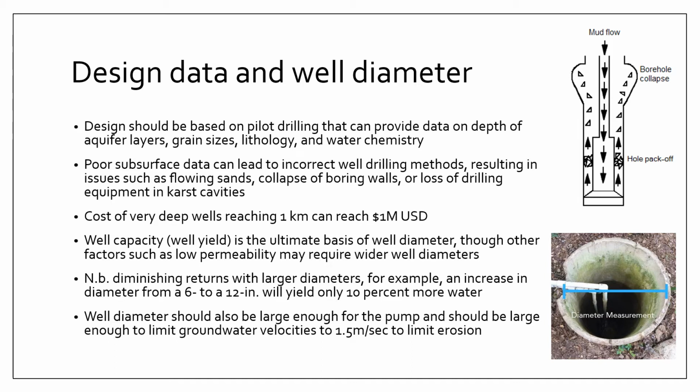So it's important to have initial subsurface data so that a proper drilling method can be used. Right? Typically, flowing sands will need extensive use of drilling casing. In some cases, it might require the use of drilling muds just to stabilize the sand, right?